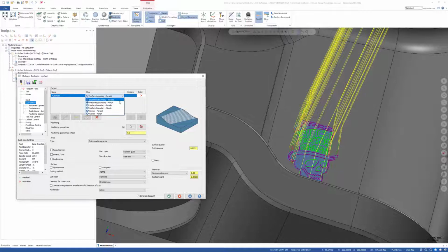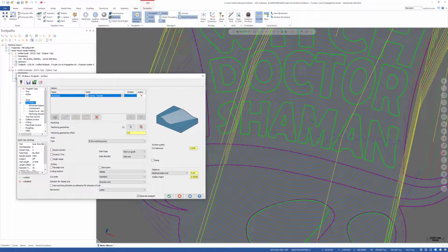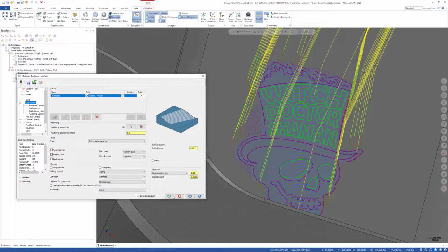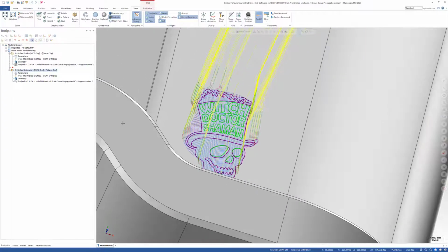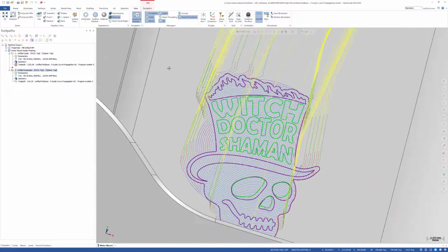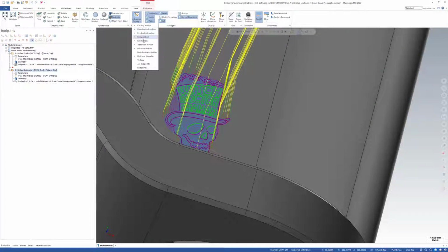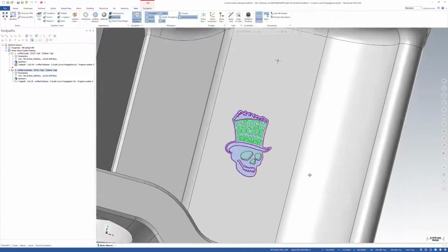We can also create something a little interesting with center parallel. What this does is Mastercam finds the exact center of that surface and simply propagates outward with circular motion. And this is actually a really cool thing to do on a trunnion machine, because this is a great way to create just that C-axis spinning motion and have perfectly concentric circles. And of course, I've got to clean up my lead-ins and all that stuff, but if we just turn on advanced display just to see the actual cut motion, there's our really simple cut motion there.